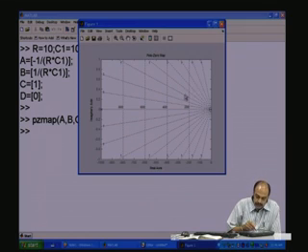These lines will indicate that as you start going towards the imaginary axis, or the omega axis, you will have larger amounts of oscillations, but which will have a rate of decay, which will gradually decay depending upon whatever the projection value is on the x axis.